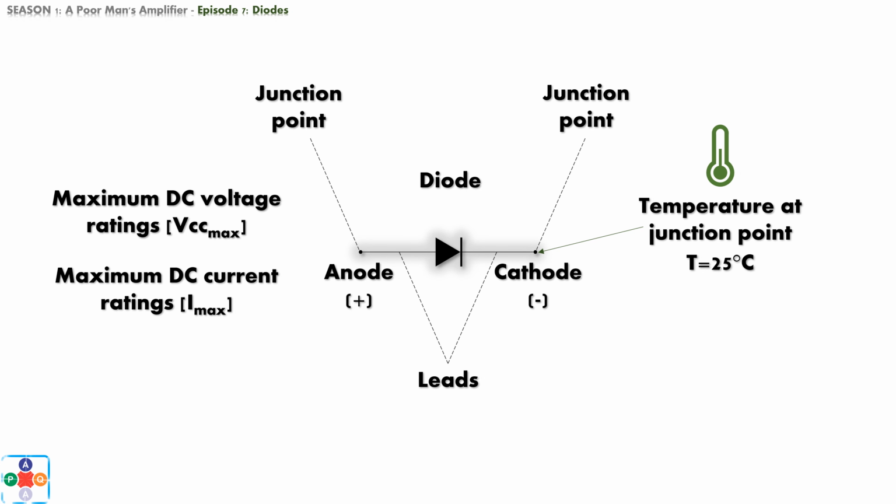Since we have not found the required info in the datasheet, there are still a few options on how to get that elusive diode voltage drop value. At the beginning of this video, we mentioned that the typical voltage drop for a silicon diode is 0.7 volts, and for a germanium diode is 0.3 volts. Now, these parameters are from so-called ideal diodes, respectively.